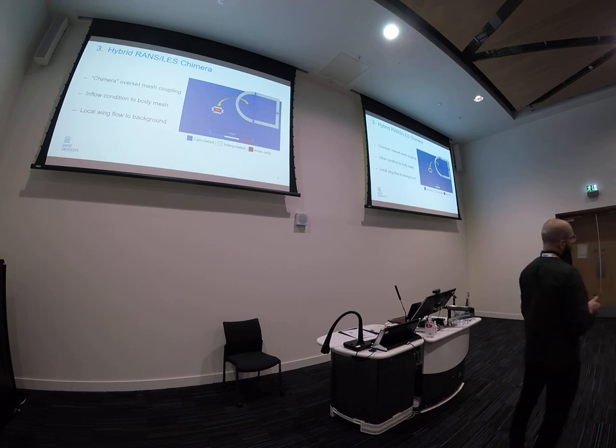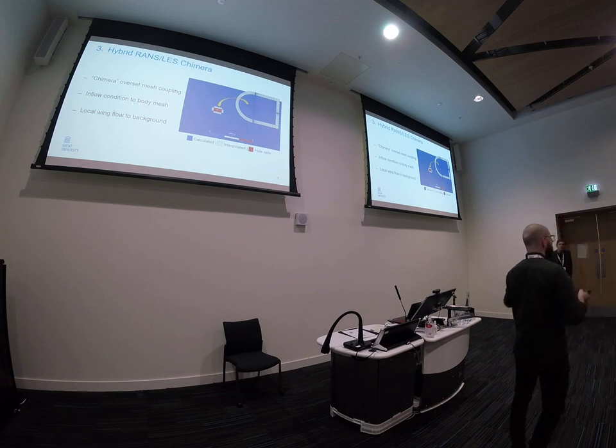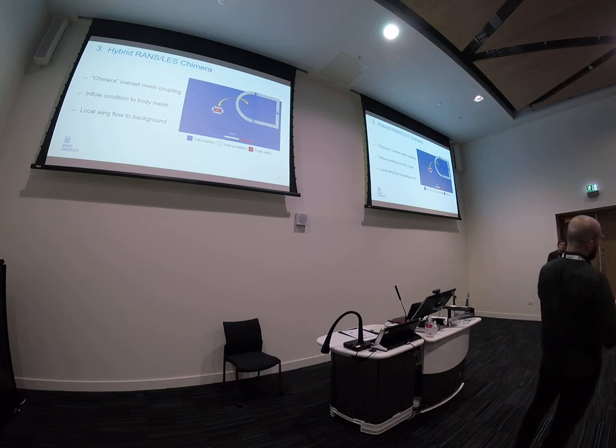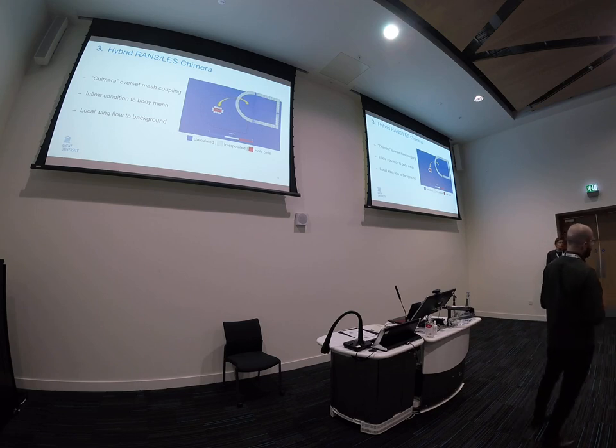So this is really something we still want to investigate, because in some cases part of the wake is really fully LES-like, but from the tests I've made, this performance really decreases when you have a coarse mesh. So it really depends on the mesh. There's some work we need to dive into to make sure that we have the right choices for the pilots.